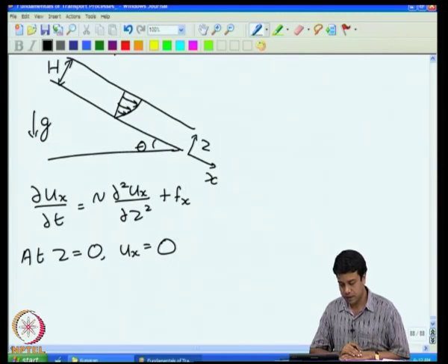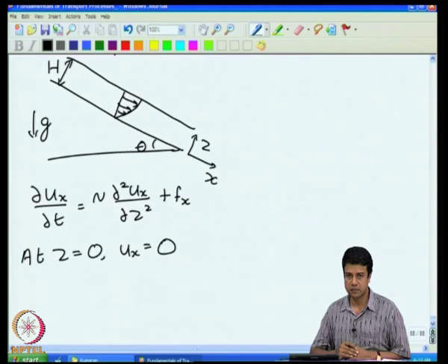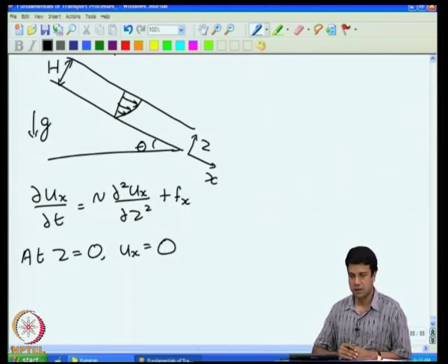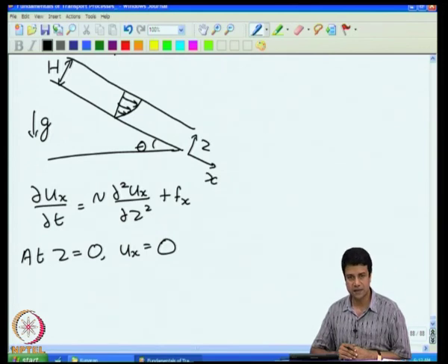At the top surface, the fluid layer is in contact with a gas or with vacuum. Even if it is in contact with a gas, the viscosity of the gas is much smaller than the viscosity of the liquid. Liquids usually have viscosities of 2 to 3 orders of magnitude higher than gases. Therefore, the viscosity of the gas is much smaller than the viscosity of the liquid. The shear stress applied by the gas is negligible compared to any stress that would be exerted by the liquid.